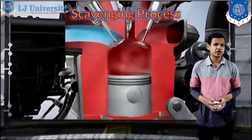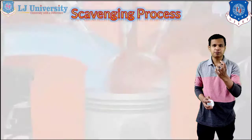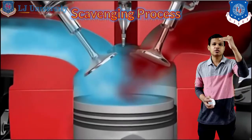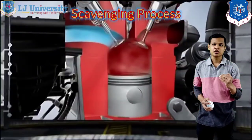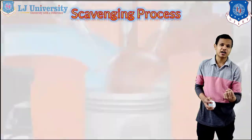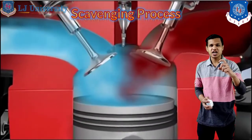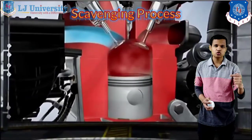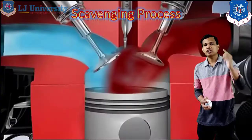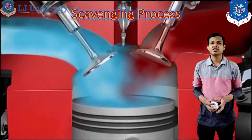So what we do in the two-stroke engine is that first we take the charge from the inlet port. After the inlet port, the charge first comes below the piston in the crankcase. When the piston moves from TDC to BDC, simultaneously the charge that came from the inlet port is compressed below the piston. That compressed charge goes through the transfer port, and when the time arises, the transfer port supplies the fuel into the cylinder part where the combustion is to be done.